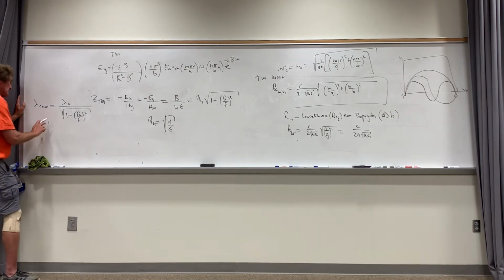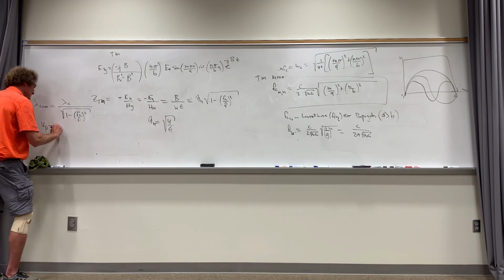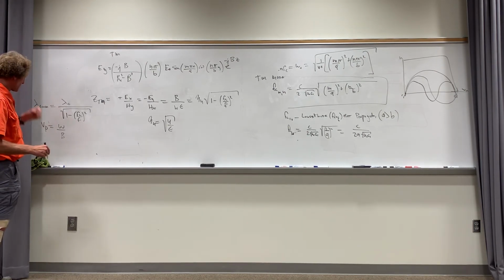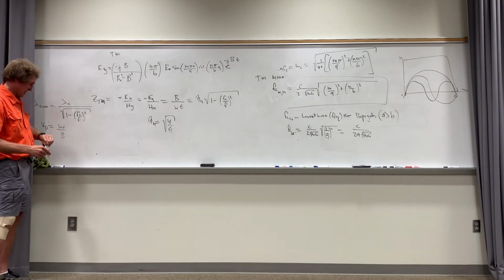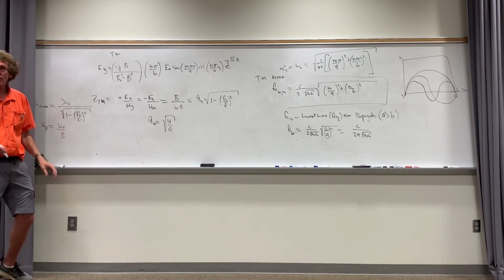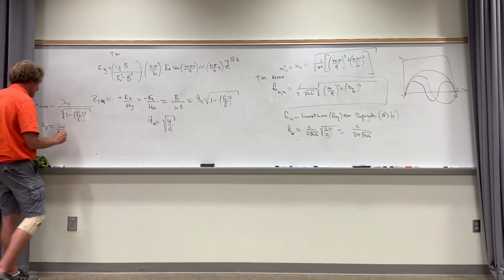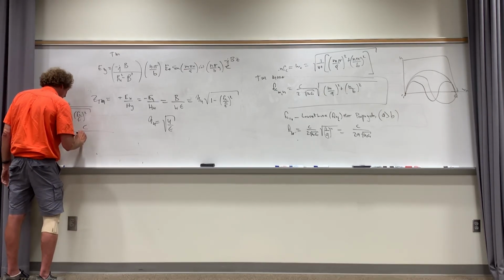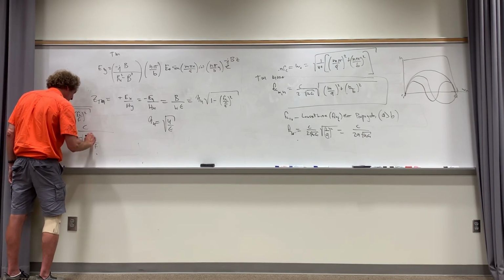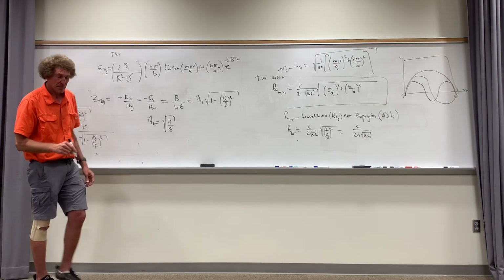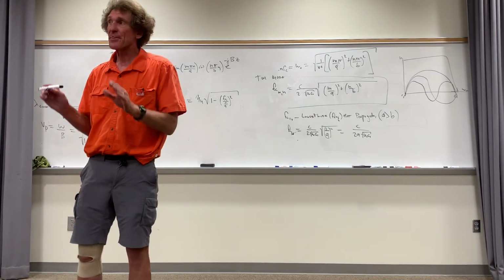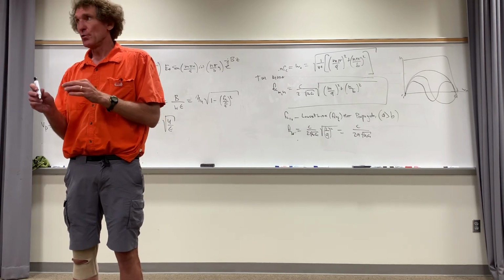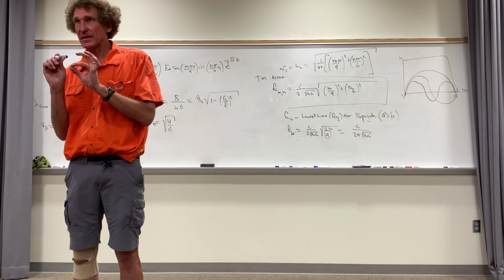Now the phase velocity is interesting. Phase velocity is omega over beta, right? Here, the beta term, well, I'm past my time, but this can go faster than the speed of light. The phase velocity, unguided, is c over the square root of 1 minus fc over f squared. And I want to tell you this. Phase velocity has nothing to do with the rate that energy travels. It only has to do with a point we call a point of phase on a surface.